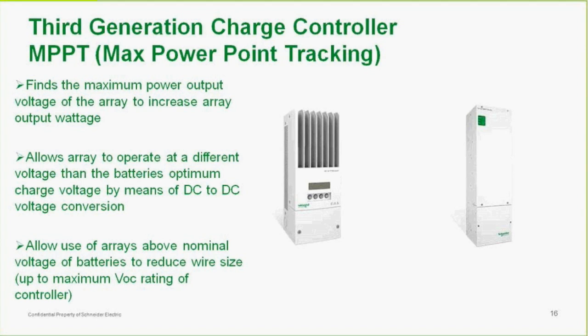Now, the reason for that is on those very hot days, that VMP, that voltage at max power, will fall with higher temperatures. So we always want voltage to be above. Now, in a colder climate, that VMP can rise, which gives us extra energy.